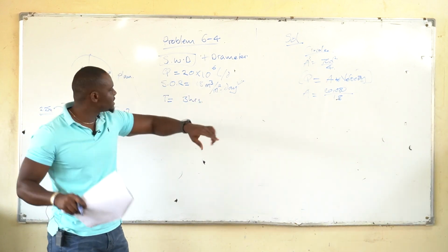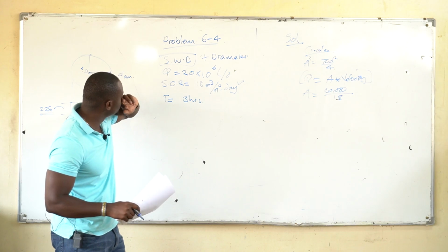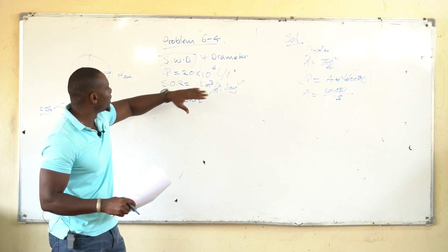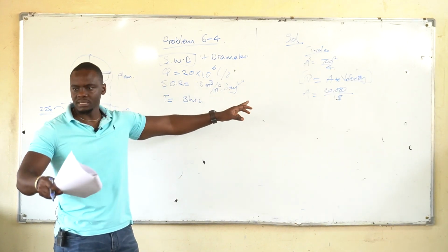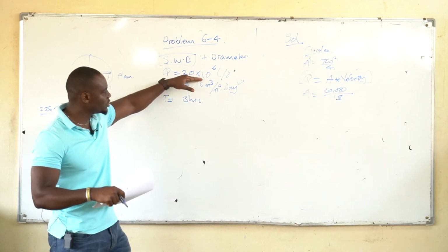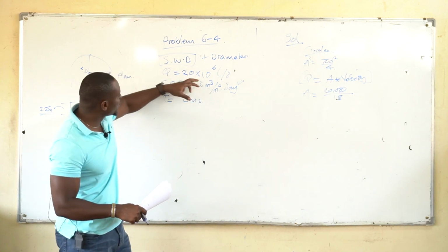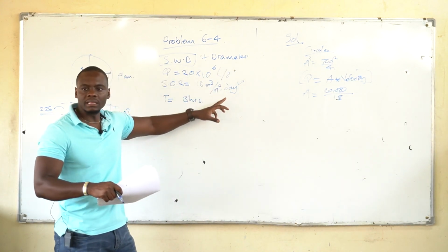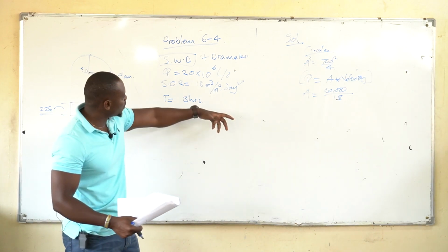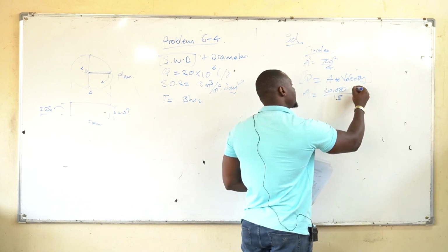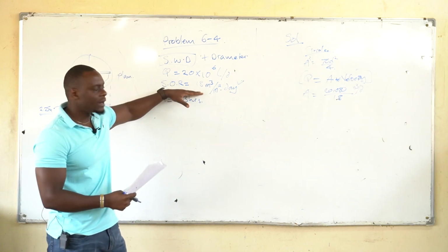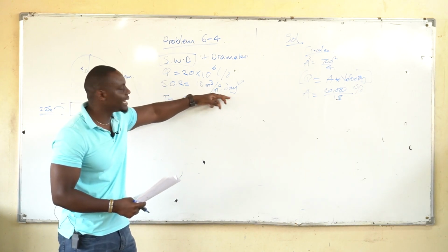The reason why you are converting your liters into cubic meters, you remember what we did to get from the 20 million to 20,000, right? It's because when you look at all the units you want to cancel, they need to align. So this value we convert into cubic meters per day. When you come to the SOR, it only has cubic meters, square meters, and a day.